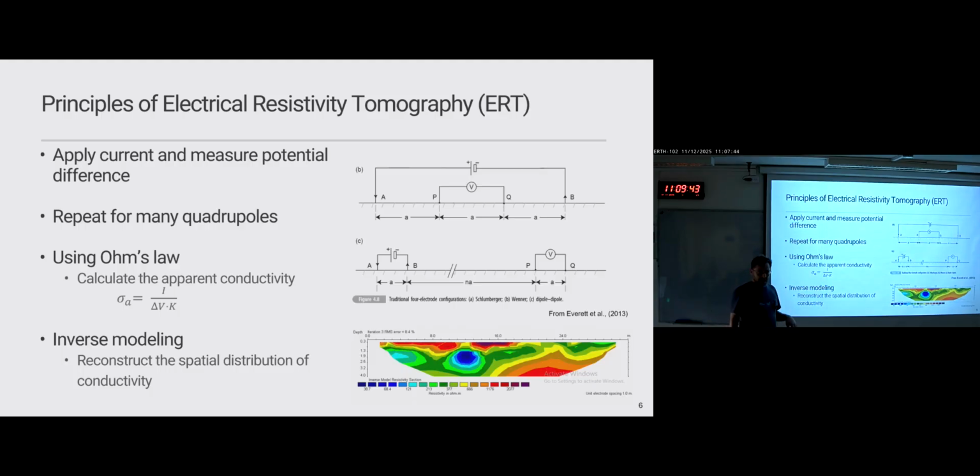But from the surface measurement, we get a 2D or 3D picture of the soil. In a typical setup, with the instrument that I have, a simple instrument, you can get to a maximum depth of up to 30 meters, something like that. What is the spatial scale of what you see there? So this is like 24 meters, so tens of meters, but this really depends on the length of the line that you install. So what is the maximum distance between the electrodes?